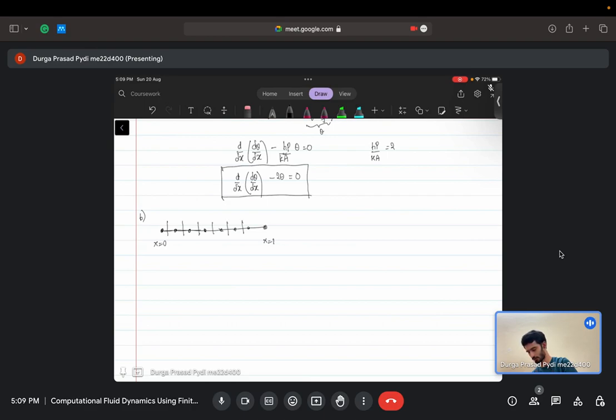For the last cell, the face will come outside of the domain, and essentially you will be having only a half control volume. For the last cell, you have the boundary point here. This is the n minus 1 cell, this is the nth node, and this is your imaginary surface extending outside the domain. So this is one way of discretizing.